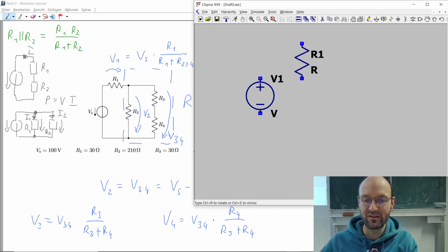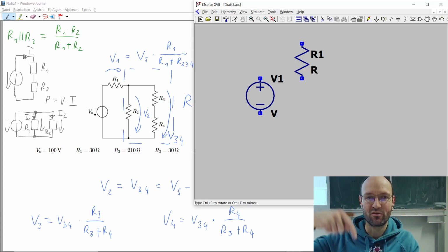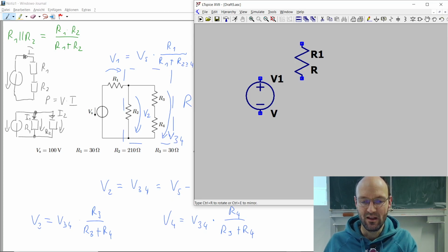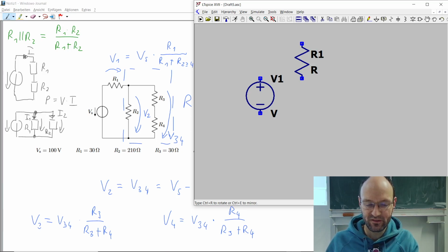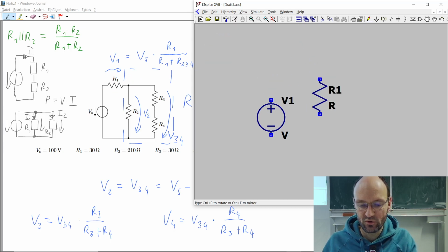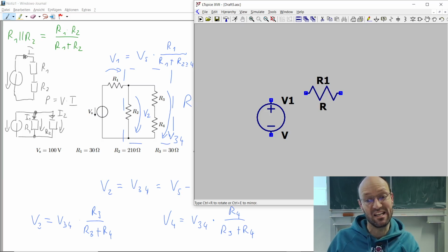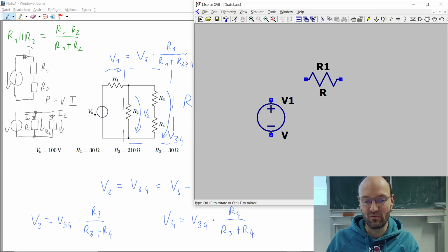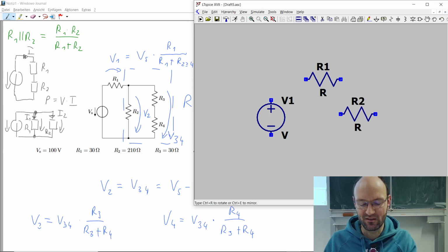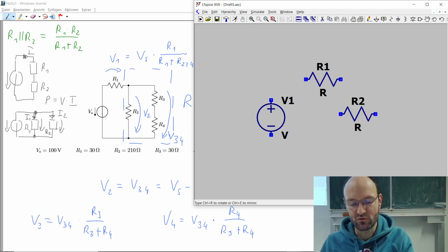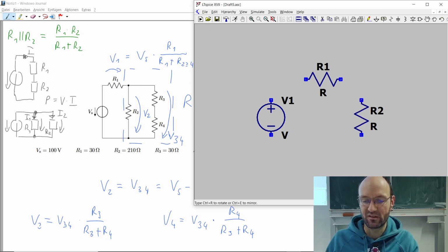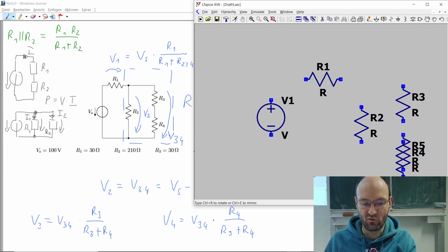And I know from experience that now the positive current through this resistor is pointing downwards. So if we want to have the resistor like over here, with some positive current pointing to the right, I need to rotate it once. Now the positive current would point to the left, upwards, and to the right. Unfortunately, the resistor always looks very similar, but don't ask me why it's like this in LTspice, but it is. And with another Ctrl R, now the current would once again point downwards. So here I will place R2, R3, R4.